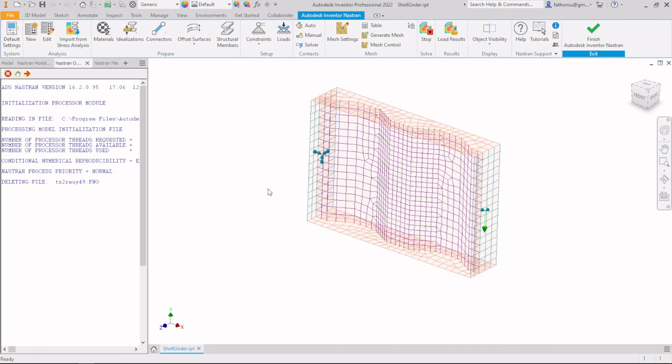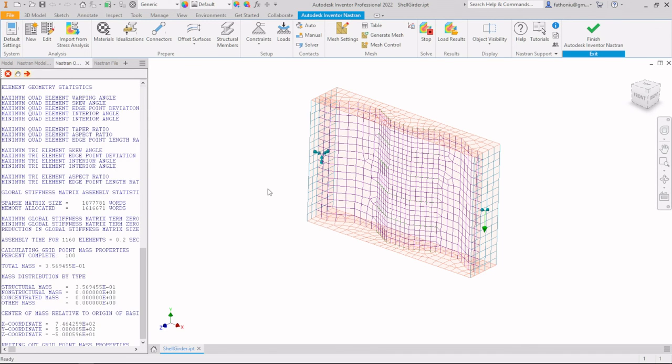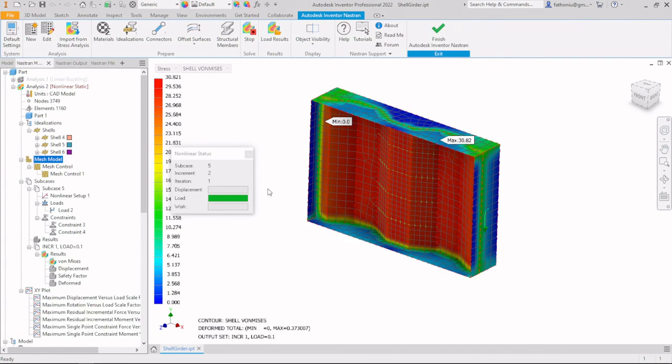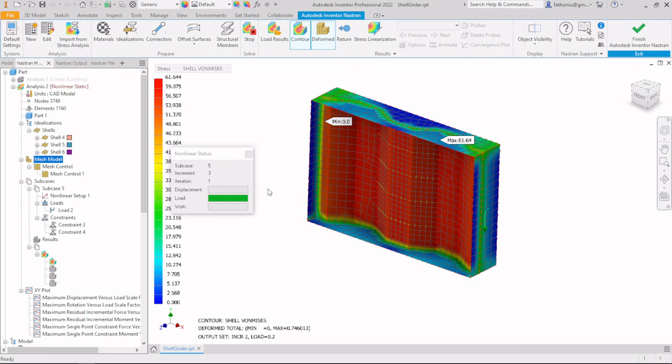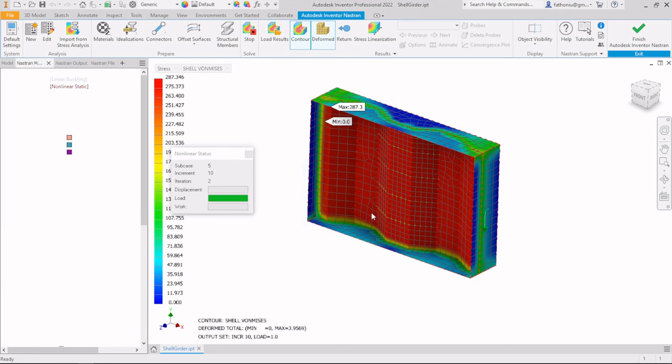It is not necessary to increase the mesh for everything, only specific areas. The analysis takes quite a bit longer because with more meshing, more calculation time is required. Done over there.